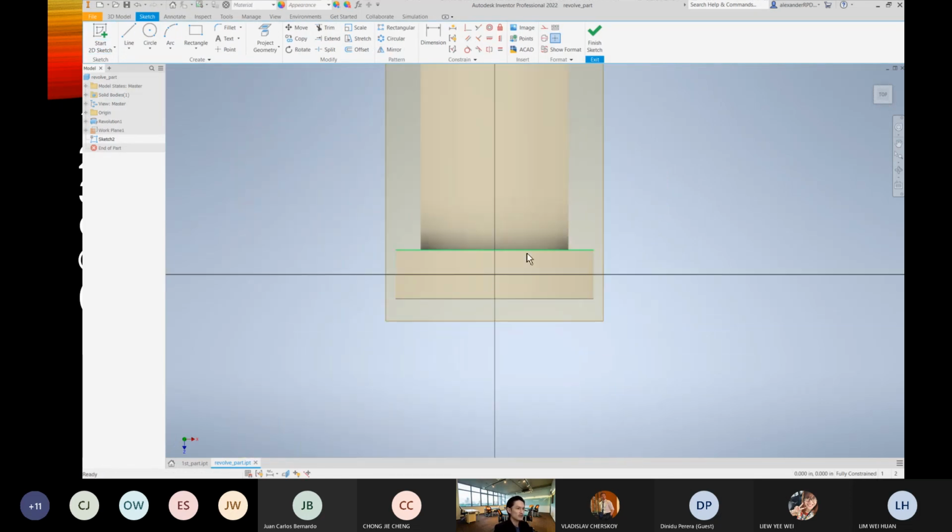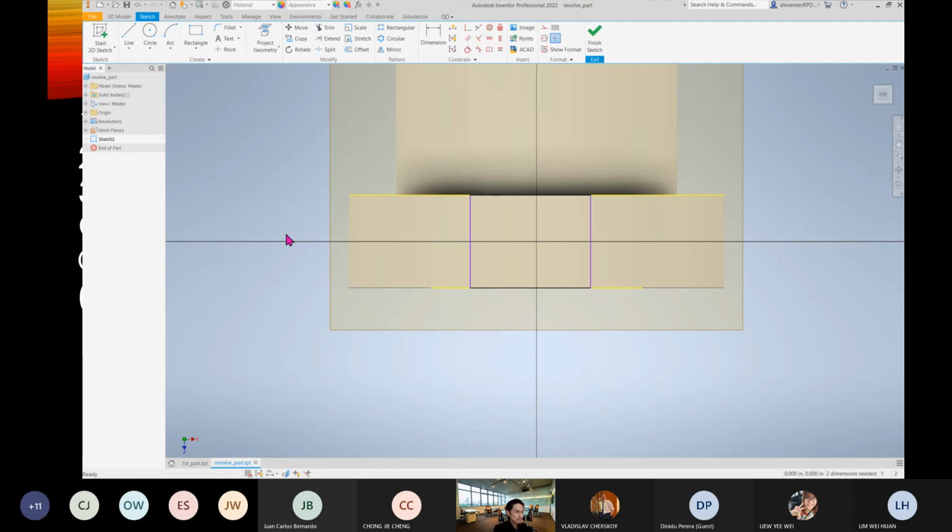I will do a keyway over here. First I will just drop a rectangle by touching it. Just now I did not borrow any line, but when I use my rectangle to touch on the edge, it automatically helps me borrow the line. You can see the yellow color there. Sometimes there is some intelligence, judging that you need that, and it helps you execute it.